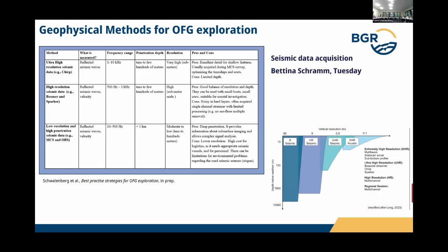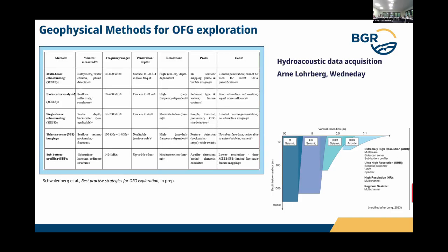There are offshore methods which use high frequency and have the highest resolution in the upper tens of meters. There's large-scale seismics which can look up to kilometers down into the sediments. And that's what we have for the seismic methods.